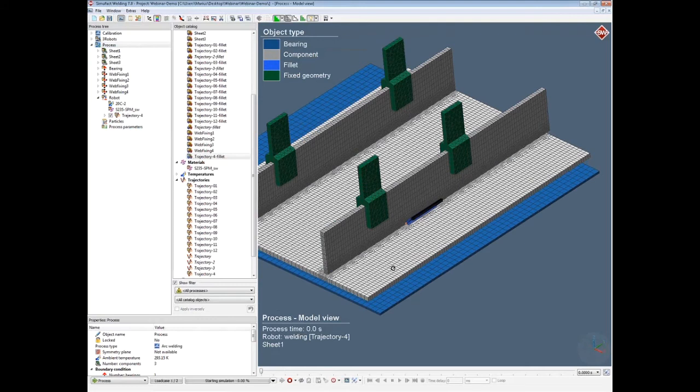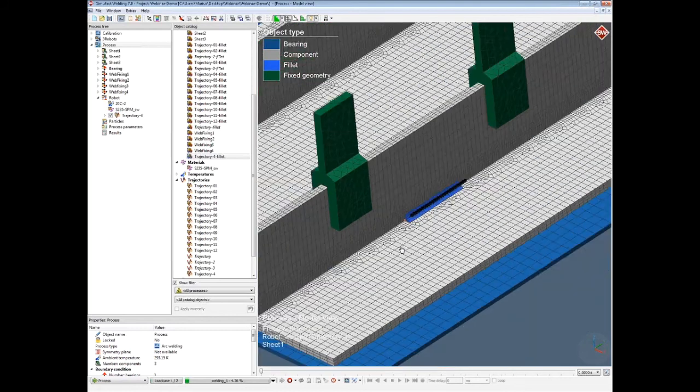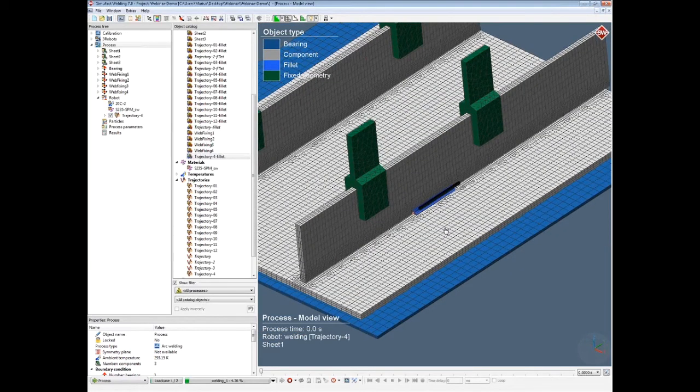This is due to the sheer fact that we are dealing with phenomena that are very localized and usually on very large structures. So in order to have a good mesh, you need to have this kind of mesh that you see here, which is typically very fine in the fusion zone, and then should be a little bit more coarse in the outer regions.